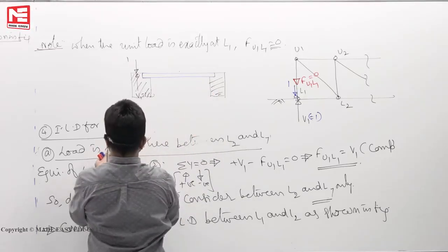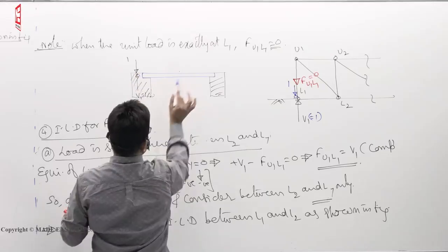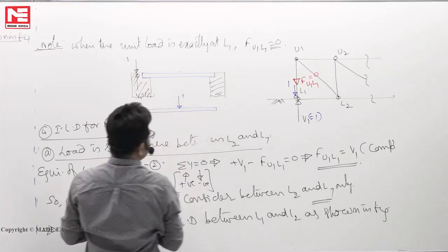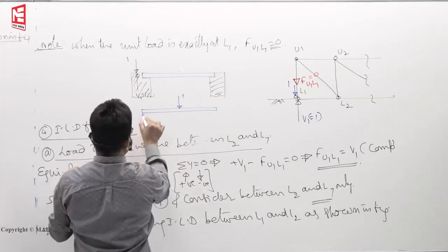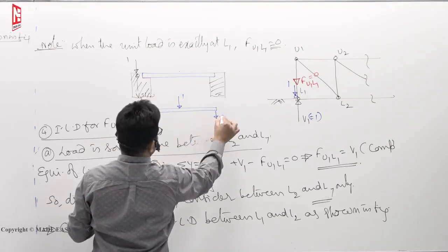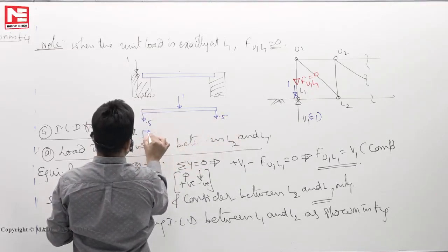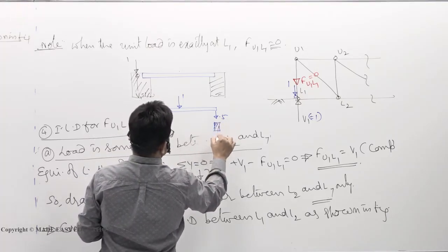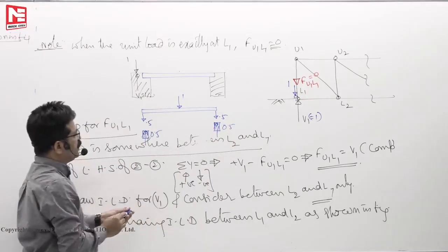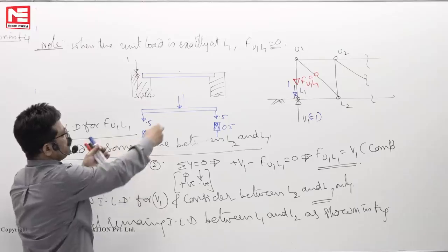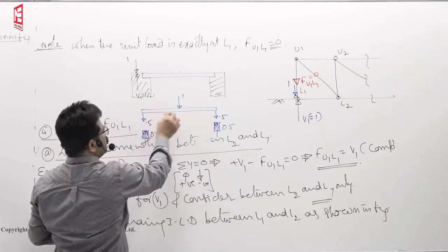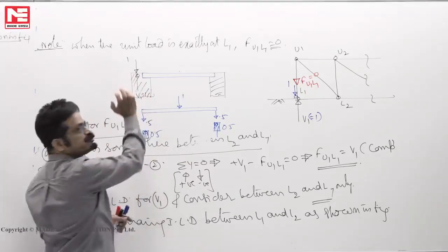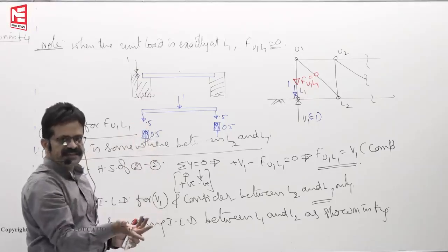So it's like this, that free body diagram. If this is the beam and the load 1 comes here, then part of the load goes here, 0.5, and here 0.5. Then the support here will react by 0.5 upward. So out of 1, 0.5 is transferred to each support. This beam will press this support with 0.5 down, so the support will not keep quiet, it will resist upward by 0.5. That's how the reactions will develop.